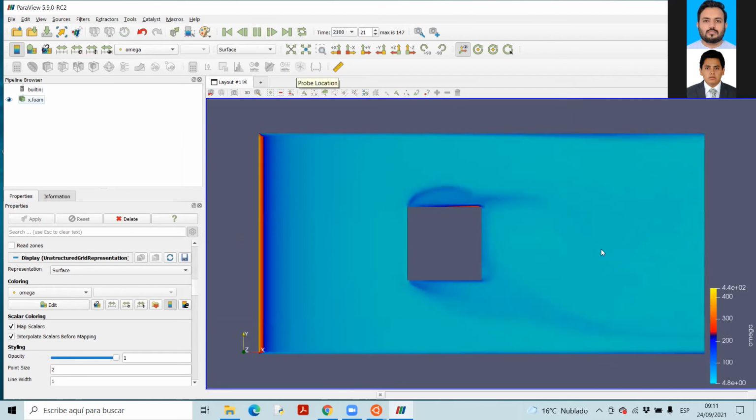Now you can see why this is happening. Because our boundary conditions are too close, due to the effect of this boundary. This is not the exact solution. This is because we have a problem with our boundary condition. We have to increase its space along the y-axis in this direction, from this point to this point. When we increase the space and move these boundaries to a large distance, then there will be no effect and it will give our best simulation.